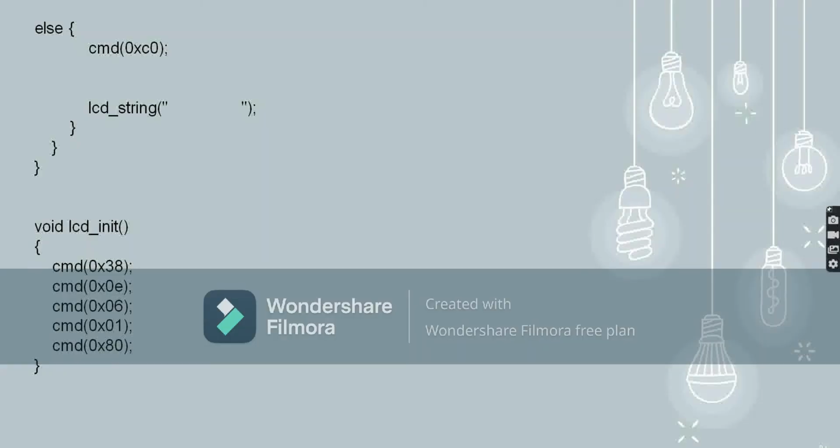When the PIR sensor is equal to 1, the program runs and we get the LCD display as intruder is being detected and the buzzer gets on, or else if not, if the PIR sensor is equal to 0, then what should we do? Then again using the command 0xC0, where it says force the cursor to the beginning of the second line, the LCD string is being null. It does not print anything, it's just being left as such.